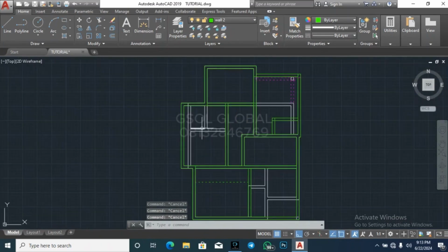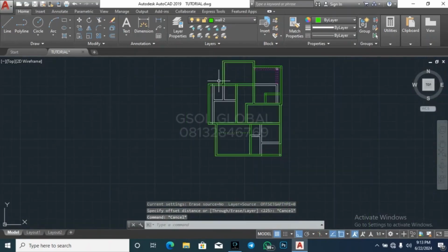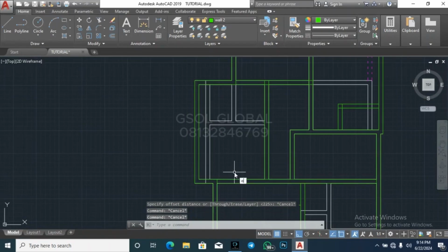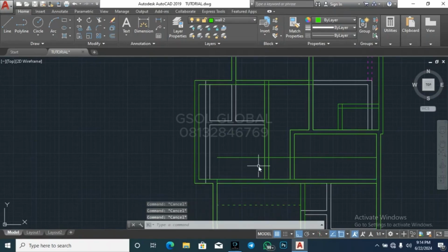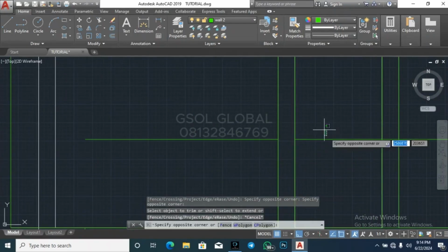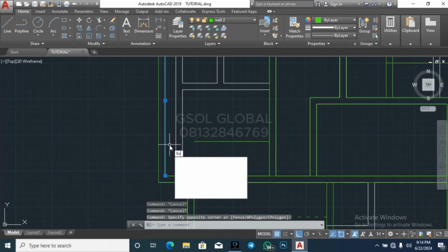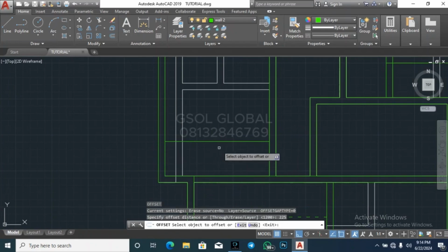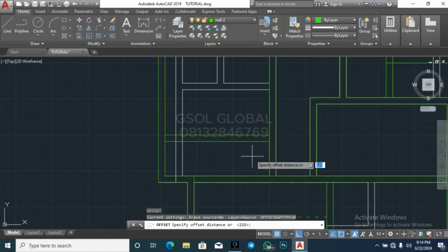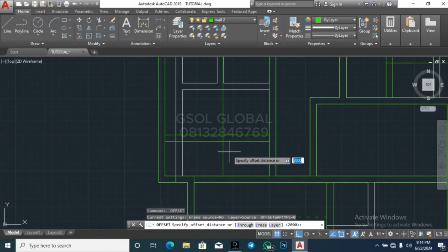So we'll go ahead and create our toilet for this. Make an offset from either point. Let's say from this point, 1200. All right. Delete this one off. Okay, so extend this to this point and make an offset of 225. All right, so now from this point, make an offset of 2 meters, then 225.